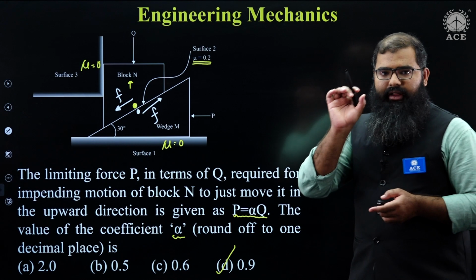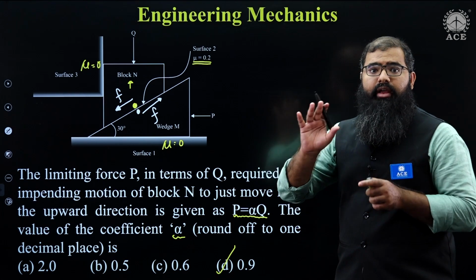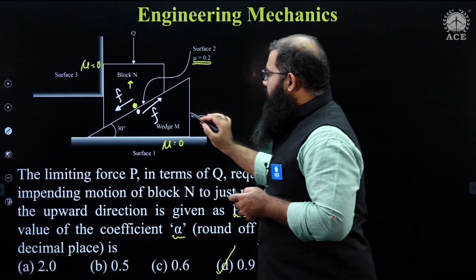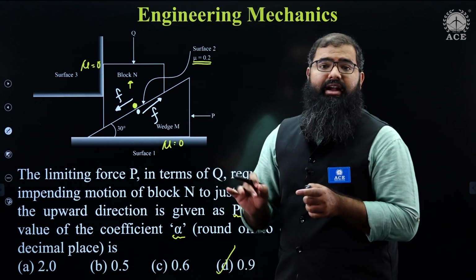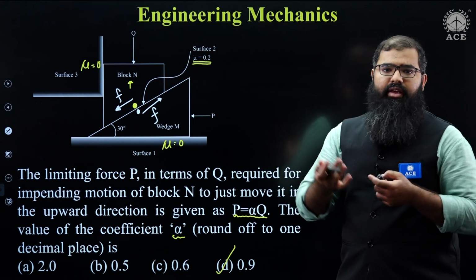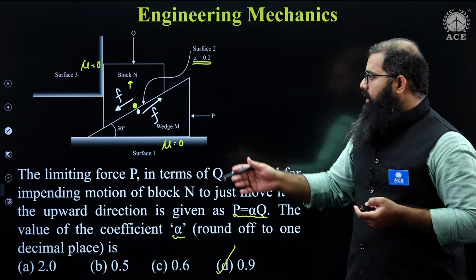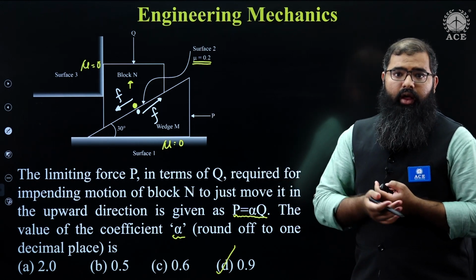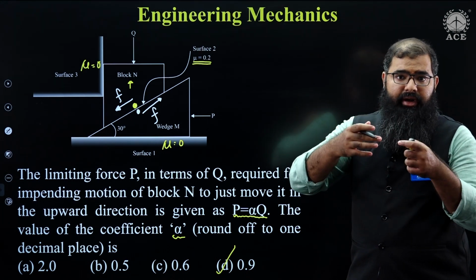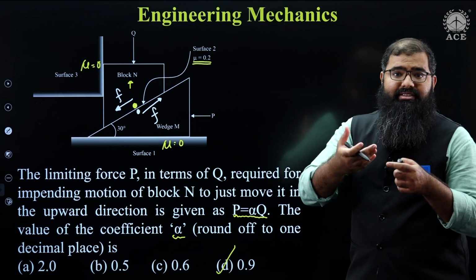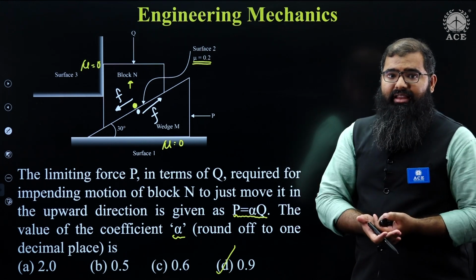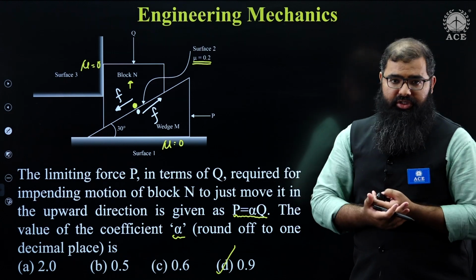Now, what is the critical point? After having completed this question, let us look at where you could commit a mistake and which point is going to be very critical over here. The most critical point is already mentioned over here. It is deciding the direction of friction. People are not worried regarding the normal directions, they get it very easily. It is only with friction they get trouble whenever you're having wedge problems. Whenever these kinds of problems come in, always think of mating particles, and when the motion is impending, try to visualize that motion and decide what is the relative motion of mating particles with respect to each other. Once you decide that, friction is just going to oppose that particular motion, right?